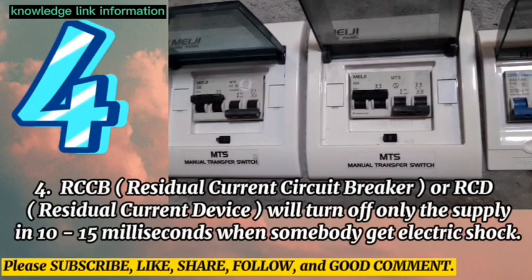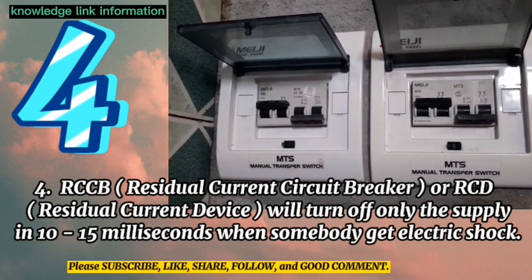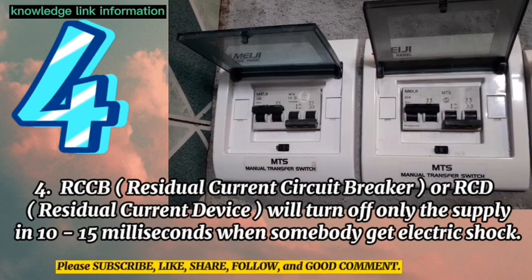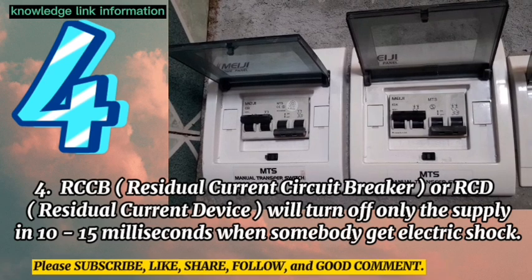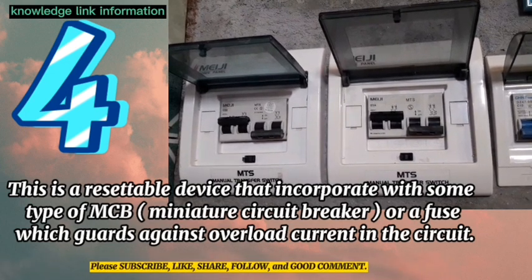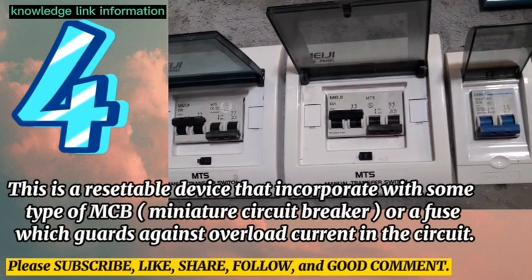Number 4. RCCB, Residual Current Circuit Breaker, or RCD, Residual Current Device, will turn off only the supply in 10 to 15 milliseconds when somebody get electrical shock. This is a resettable device that incorporates with some types of MCB, miniature circuit breaker, or a fuse which guards against overload current in the circuit.